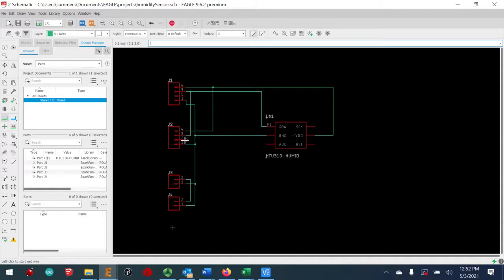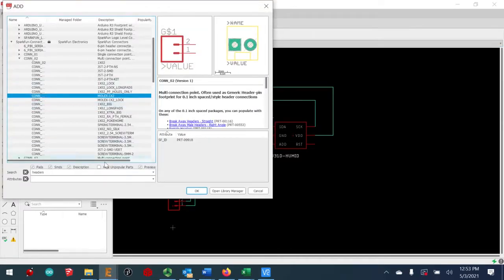Anyway, in addition to the serial data pin, we also have the clock pin. All right. Let's see. The rest of these things, these two, the address and the reset pin, they're both going to be just pulled high. And we're going to pull them high with a resistor, a pull-up resistor. Okay, so we need to put the resistors in there.